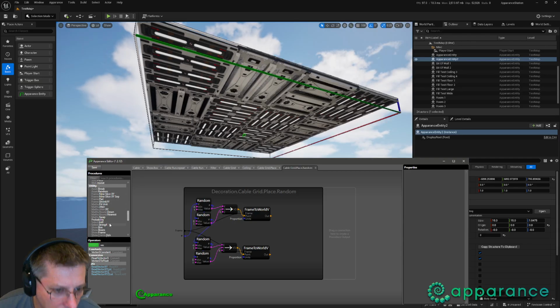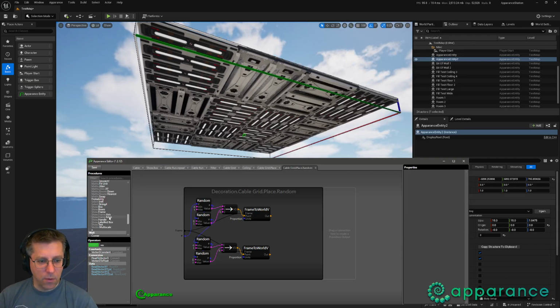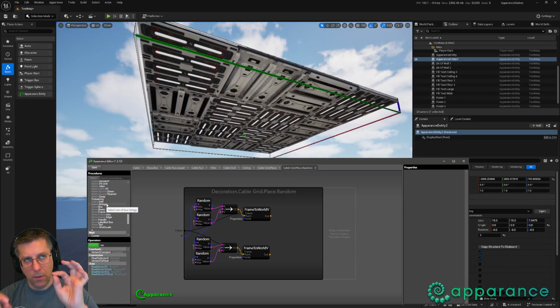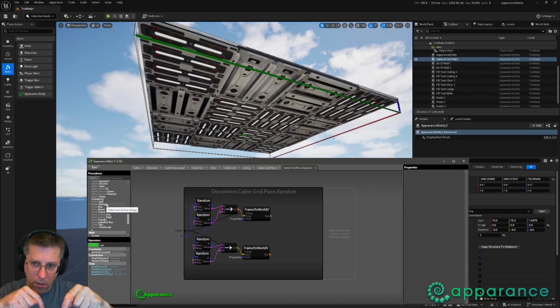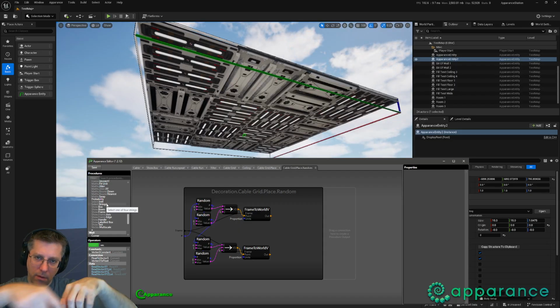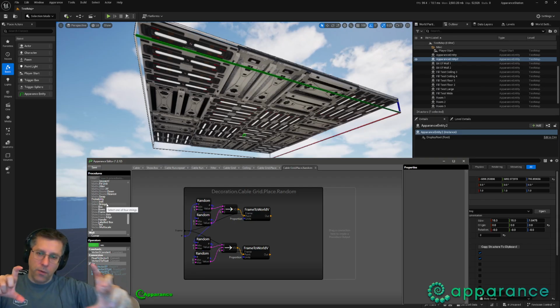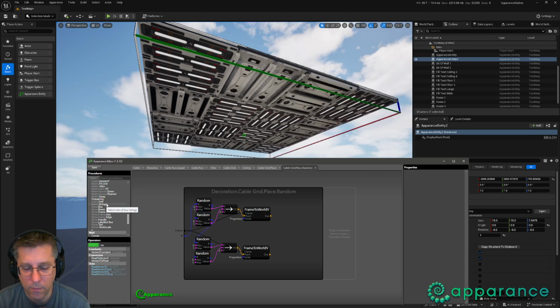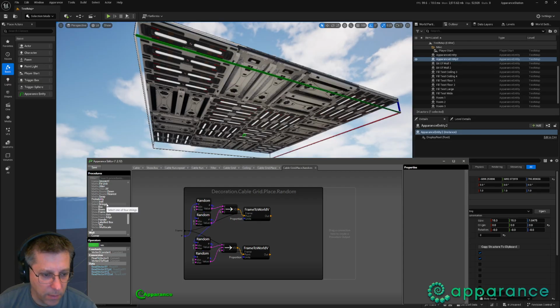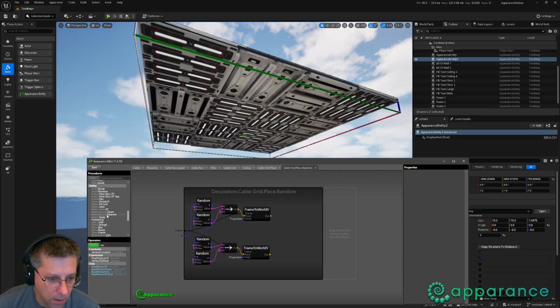No, we haven't. So something I've built before a number of times is a utility to build a frame between 2 points. It's useful if you're following a polygon, like a perimeter, you can build frames along each edge, and then you can throw a wall procedure or something in there. I haven't got one in here because we haven't needed that. Our rooms have been rectangular, so I might knock up that because that's quite a useful utility.